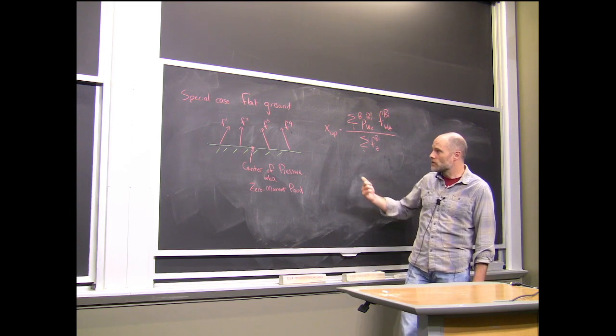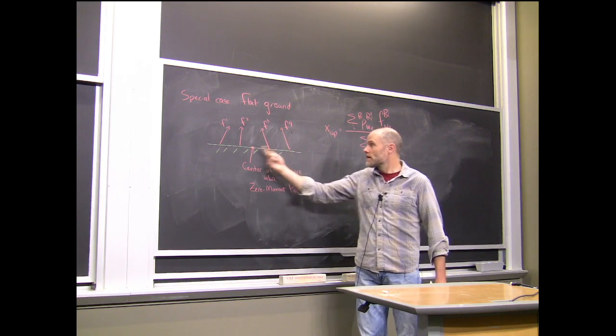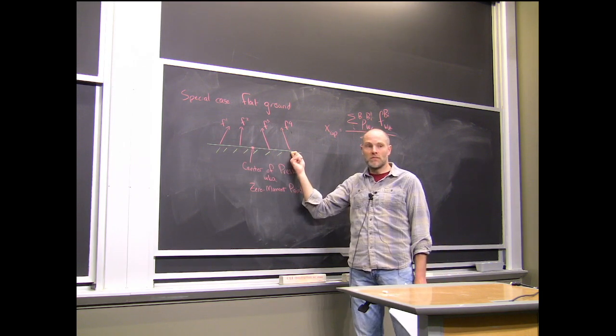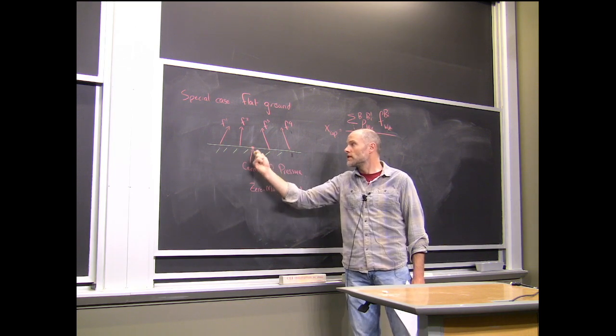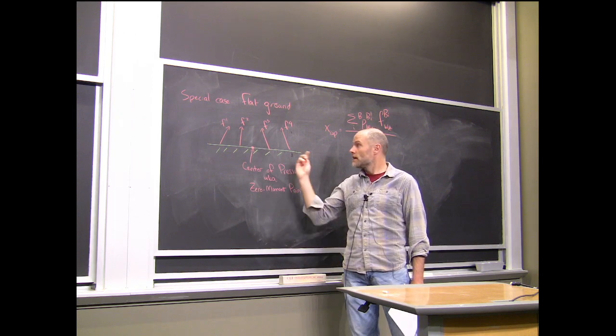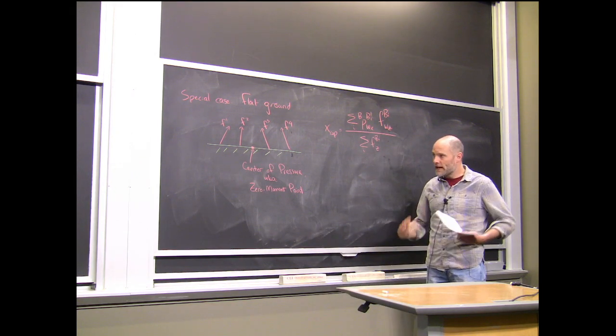So it's sort of natural, right? I want to summarize: if all of the force was here and everything was small, then I want my center of pressure to be here. All the forces here, right? This is just a way to interpolate and take a weighted average of those forces, very analogous to the center of mass.